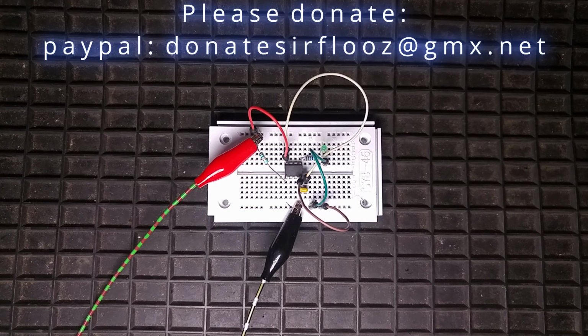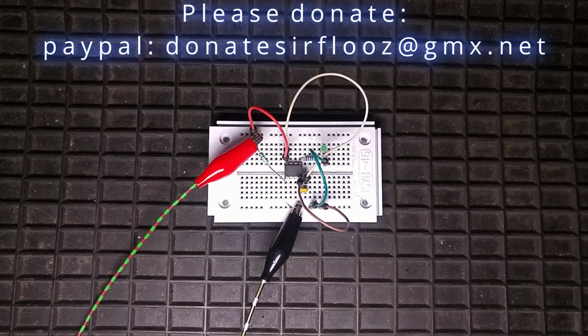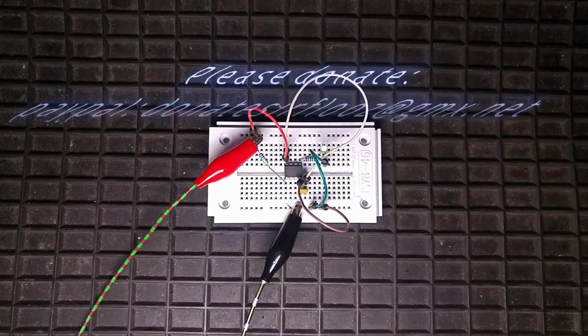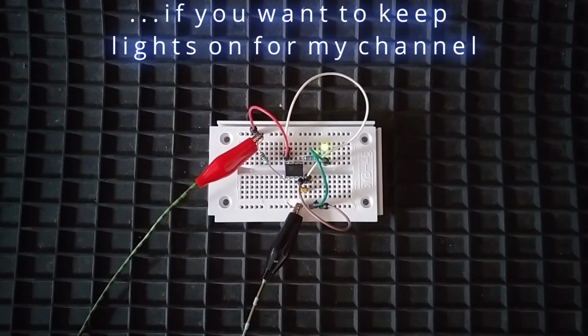I'm really happy that this test works so successfully, as the clock relies on a simple RC oscillator, which consists of a resistor and a capacitor, as the timing parts of the frequency can be a bit off. In timing critical applications, this can be an issue. I will probably try to measure and calibrate the clock of the ATtiny for an improved performance.